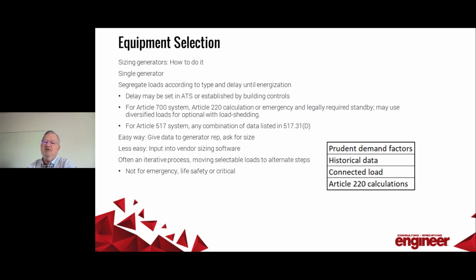Now, the easy way to get the generator size is to give the data to a generator sales representative and just ask him to size it. The less easy way is to learn to use a sizing program and do it yourself. If you do that, it can be easy to overlook something. So if you're not very experienced, it's best to have someone review the inputs and the results. Either way, it usually is an iterative process with a lot of back and forth, and it can take longer than you might think.